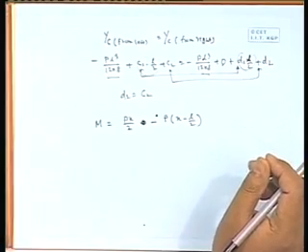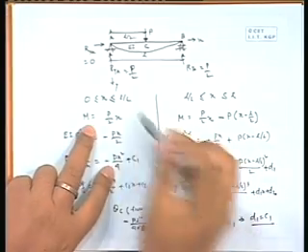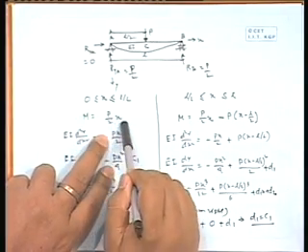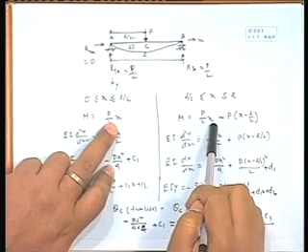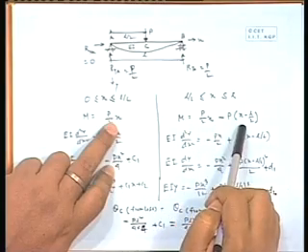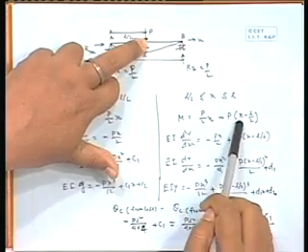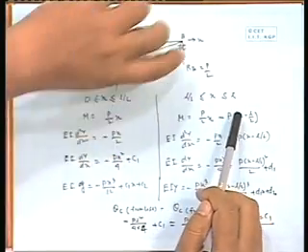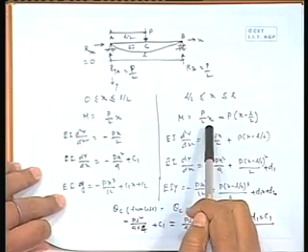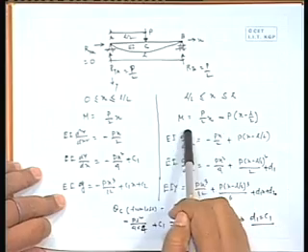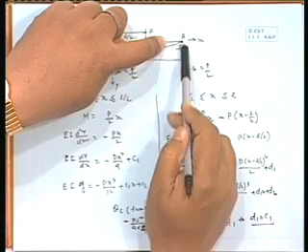Extreme reaction, it will not come in the second part. Say, here to here M equal to P by 2 into x, and here to here it is, say this force into x, that part is there, minus P into x minus L by 2, because here if it is x, so L by 2 minus, that is the distance PL minus xP, that part it will give a hogging moment and this part will give some sagging moment. But this RB will also put some moment at that section. Yeah, because these two forces will give some moment, that moment will be balanced by RB.